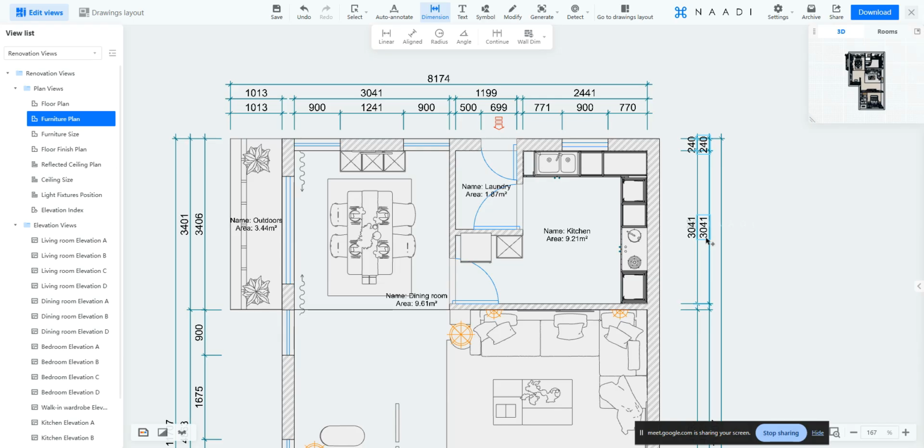Okay, if you want to add something in 2D, please go to your model window, add it there in the 3D and come back to the 2D drawing, it will be updated here. But only in the 2D alone, you can't add something here. Any furniture, anything, you can't just add it in the 2D alone. It needs to be there in your 3D, that way it will get updated in your 2Ds.